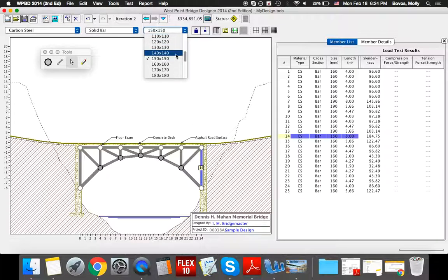It's still okay. 140, and you can try making those changes and see where's the limit where it becomes too skinny. Looks like 110 is still acceptable. Oh, see, stupid selection thing. How about 90? Oh, okay, so 90 is a problem. Let's try bringing it back up to 100. Okay, so it looks like 100 is kind of the limit that it's going to allow you to make it as skinny as you can.